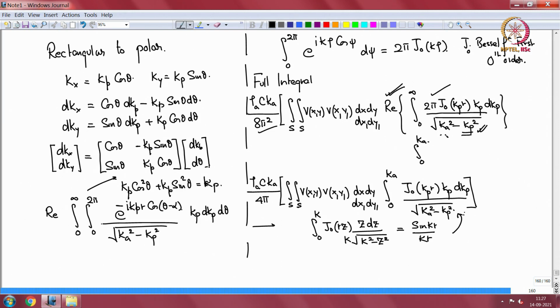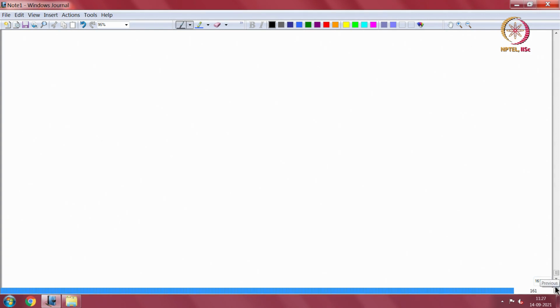Okay. So, now what happens? What that does is we get this power integral. We are continuing with that: P_W equals rho a c (ka) squared, see the squared coming in, that is because of the extra k in the relation we have used.